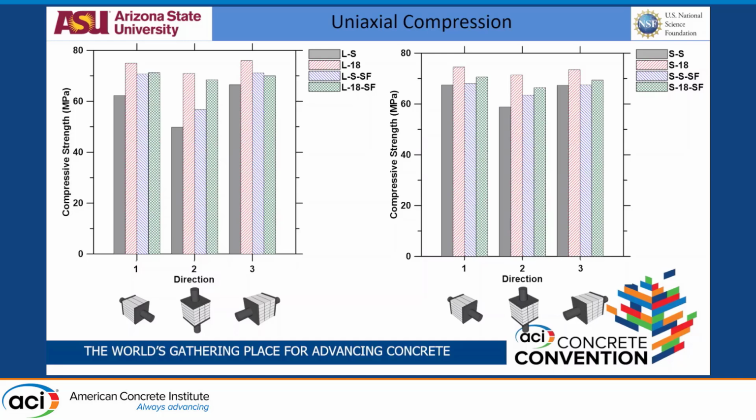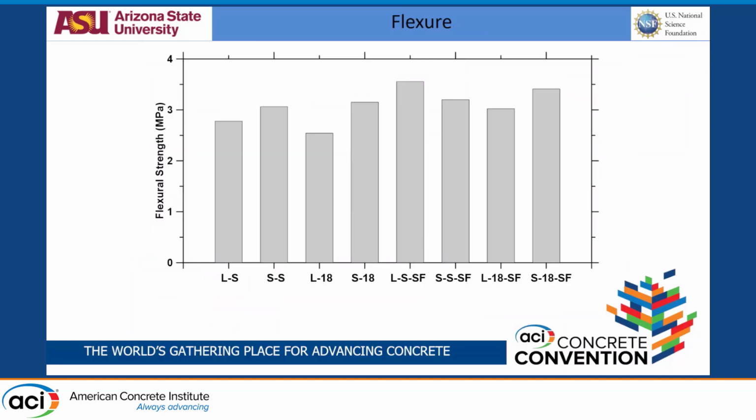But as we saw before, angling the fibers relative to the length of the beam deteriorated our strength, right? So does it happen here? The first layer is at 0 degrees, so the layer in the maximum tensile response is still aligned along the length of the beam. It's just the layers above that are slightly angled from the length of the beam. So what's the effect of that? To see that, we tested flexure for these samples too.